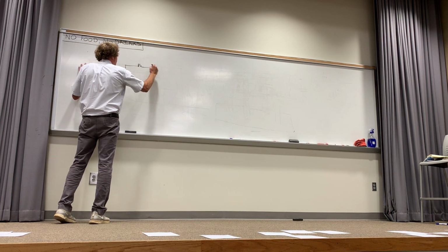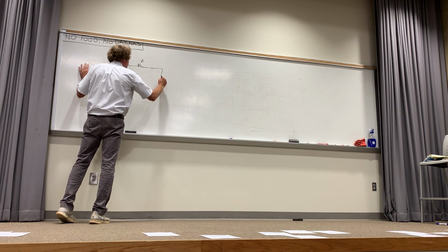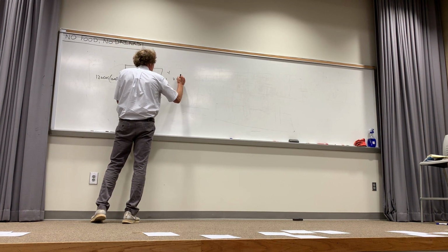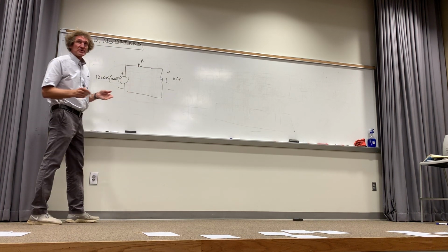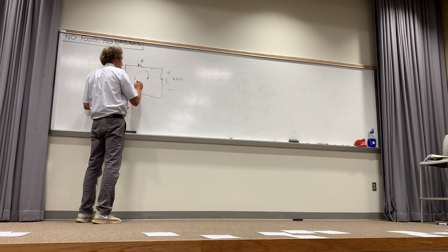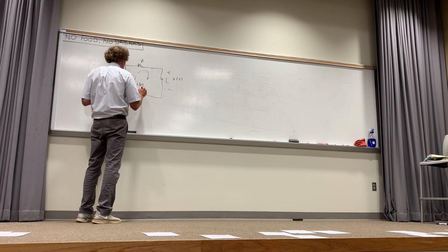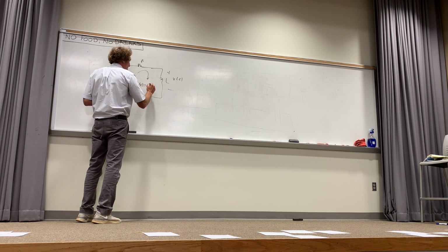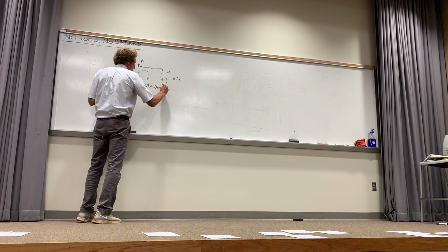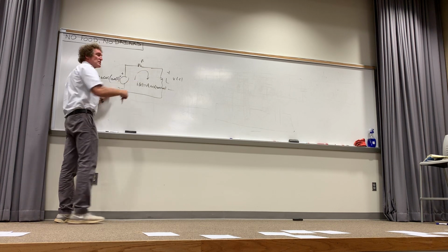And then you're going to have a resistor R and say an inductor L. And if you want the voltage here, V of t, a typical physicist would get it this way. He would assume that I would have a current I of t that would have a cosinusoidal variation, some magnitude, cosine of 120 pi t plus some phase angle, and he would write the differential equation and solve it.